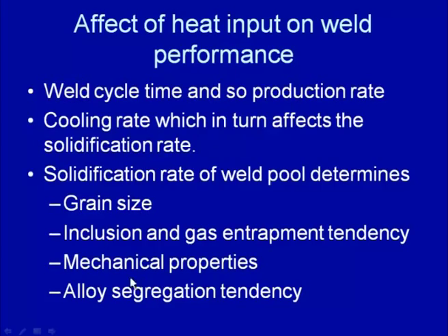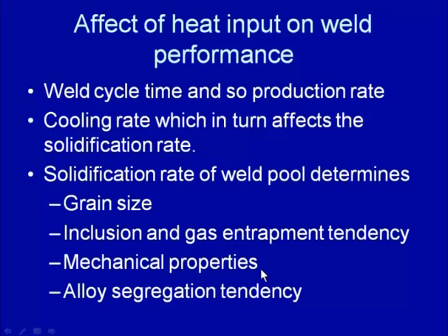While in case the inclusions and gases are entrapped in the weld pool, despite having the finer grain size, the mechanical properties can deteriorate significantly, especially the notch toughness and fatigue performance, where these sites act as locations of high stress concentration, which in turn will decrease the mechanical properties in respect of fatigue and notch toughness.